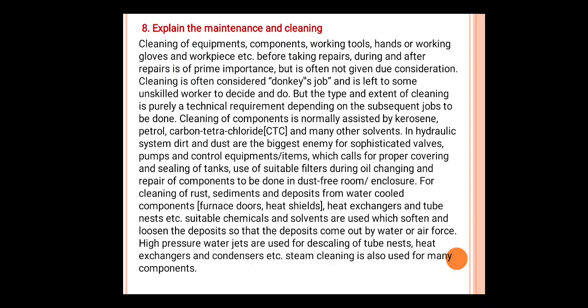In hydraulic systems, dirt and dust are the biggest enemy for sophisticated valves, pumps and control equipment items, which calls for proper covering and sealing of the tanks, use of suitable filters during oil changing, and repair of the components to be done in dust free rooms. Enclosure for cleaning of rust, sediments and deposits, heat exchangers and tube nests, etc.